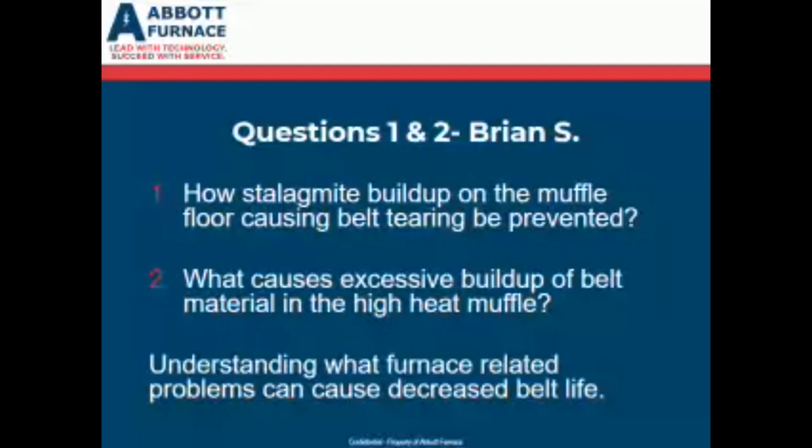It actually forms into carbide. And then with the friction of your belt and the weight of your parts holding that belt over that carbide, it eventually rips the belt or shreds the belt. And then you have to go in and replace it and put a new one on.